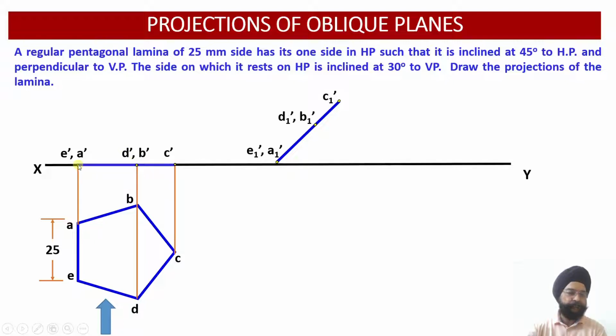These points, number 1, 2, 3, these distances will be marked, and we are going to draw the same edge view over here which was drawn over here. This will be translated or rotated at an angle of 45 degrees. Please check, this distance will be equal to this distance. Similarly, this distance will be equal to this distance.